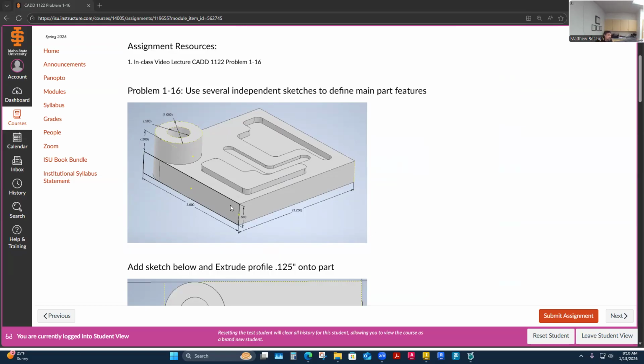You could have done the square extrusion, half inch thick, and neither would have been right or wrong or better. In fact, when I look at a shape like this, I would tend to draw it as the square shape, not the little skinny rectangle, and extrude that way. I would start with a 3 1/4 by 3 inch square and extrude it a half inch up and then start working. That probably would have been my natural flow, but either way is fine.